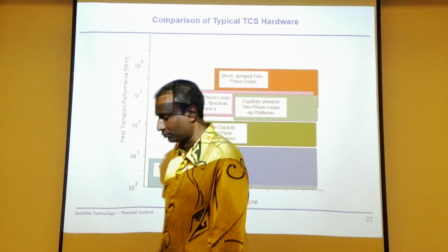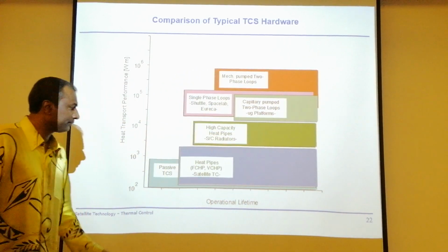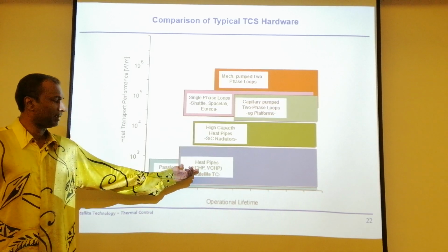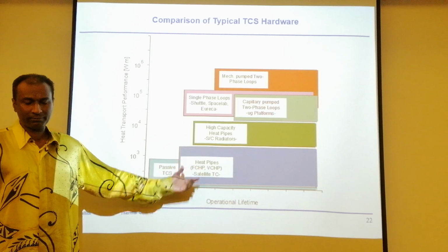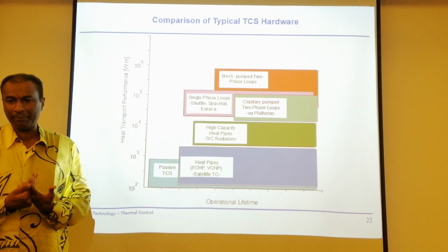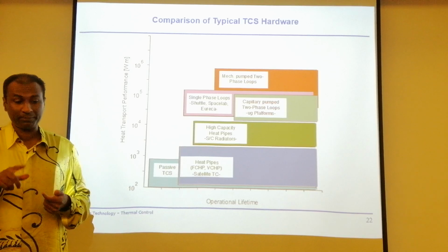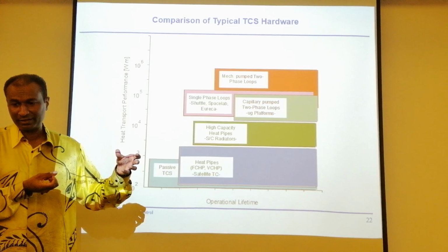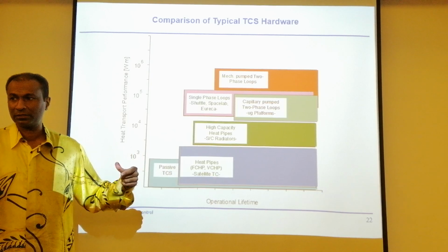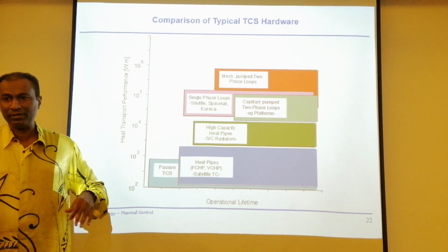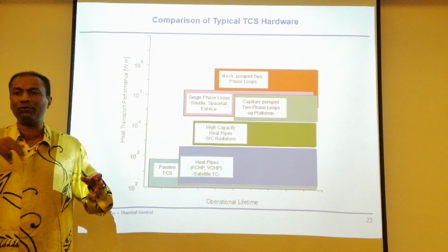Another one, passive control system. Passive thermal control systems are practically, if you have a heat pipe, and you don't fix a pump to the heat pipe, the flow is still going to happen because there is heat, and because of the capillary effect in the heat pipe and the surface, together with the surface tension of the liquid, you are going to have a very passive flow.